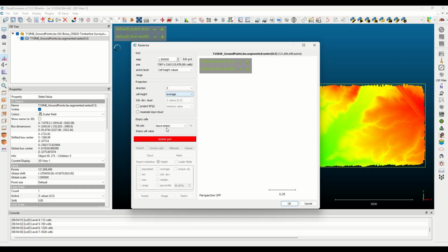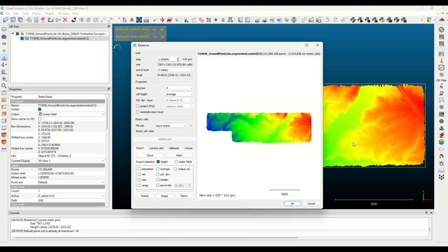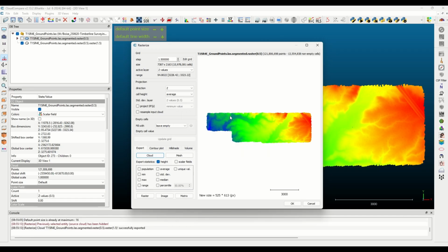And we're going to do the average. I've been asked to do 2-foot contours on this project, so this 1.5 sample is going to give us a much closer representation to what the actual ground is going to be doing, since we hunted for minimum first, and then now we're going to do an average to smooth it.